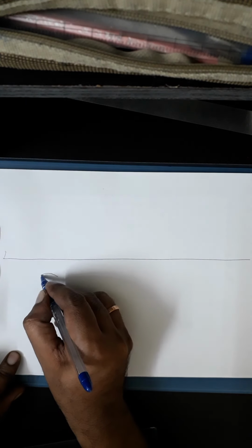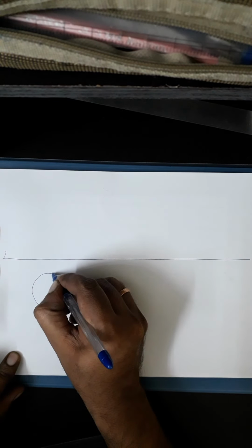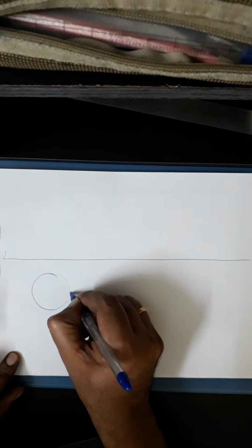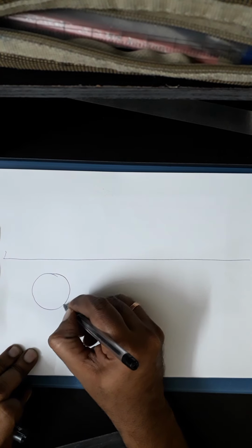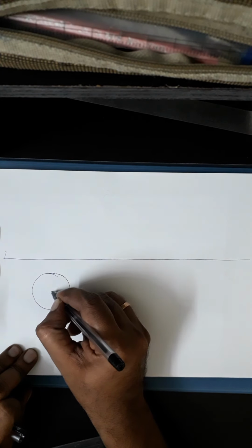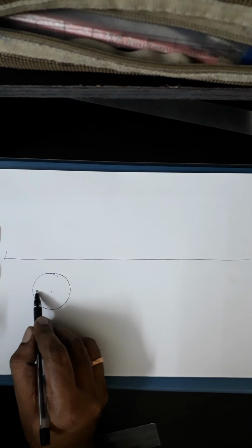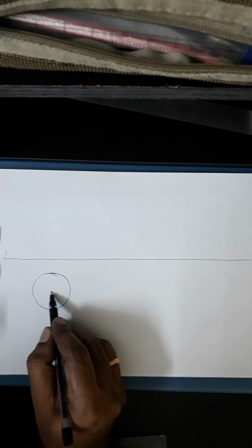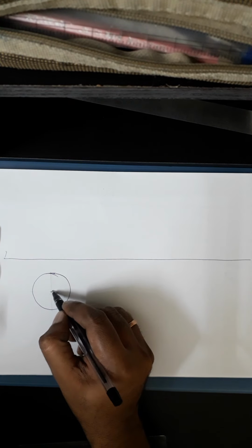Whenever I have a cylinder resting on its base on HP, the first condition, always divide the circumference into a minimum of 12 parts, as in the case of a prism.